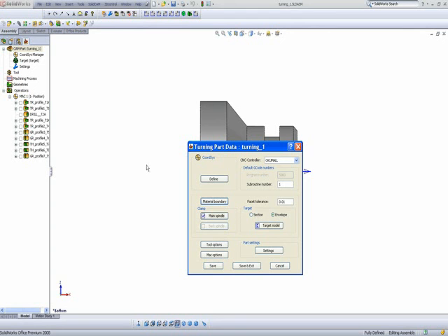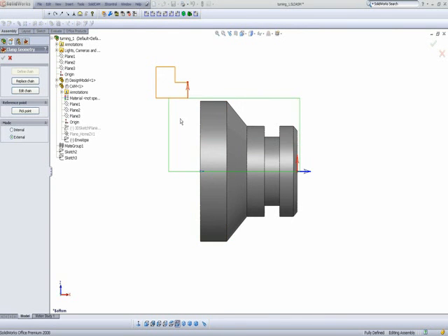My next thing is I must create a clamp, in other words, the actual chuck of the spindle of the lathe itself. Again, I must create a sketch around, and this sketch must touch or overlap the material itself, and then I simply define my chain.